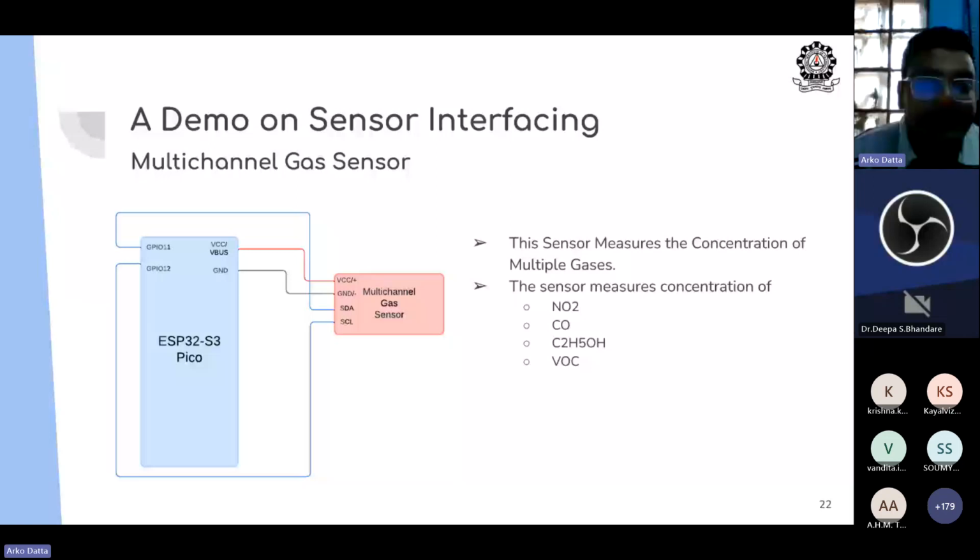Now how will we know the ground truth? For that there are high quality sensors which are costlier, and which are used by air quality monitoring stations. We can use a method called co-location, which is basically asking permission from the government and placing our sensor near that air quality monitoring station, and whatever values they show, that is the ground truth, the absolute value.